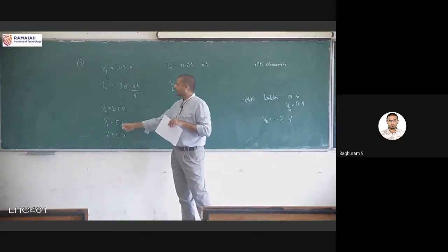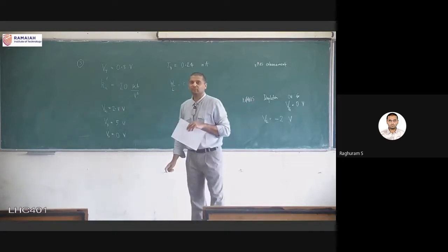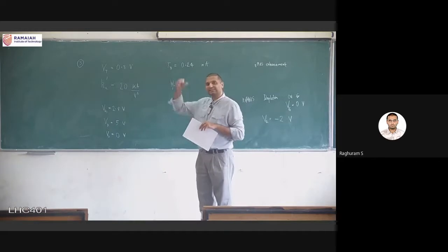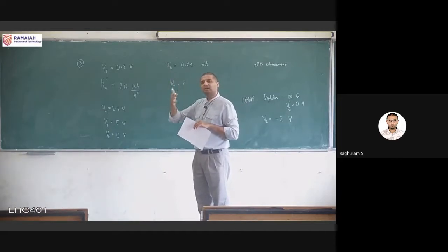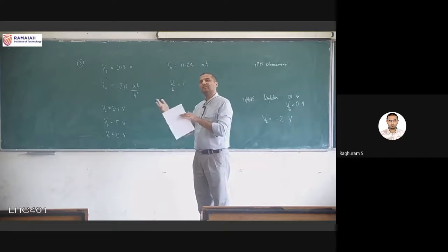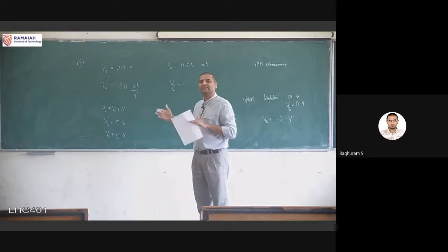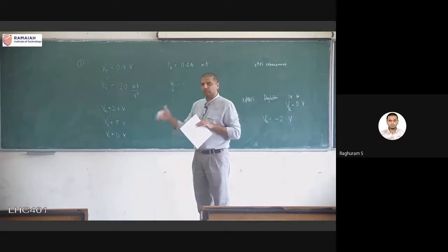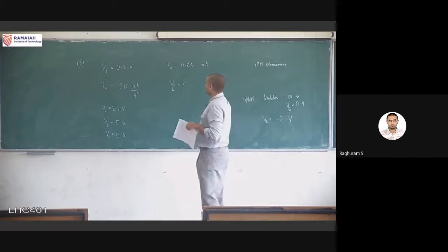But in addition, is it in linear or saturation? That is the question. Clearly Vds is higher. Whenever Vds is higher, you have to remember that automatically means the transistor might be more in saturation. So here also Vds is greater than Vgs minus Vt, which is 5 versus 2. So the transistor is in saturation. Okay, so then write down the current.